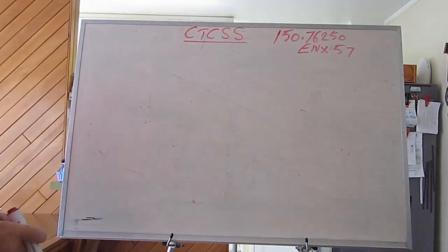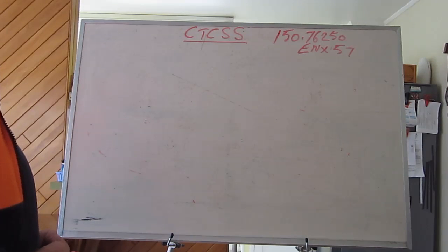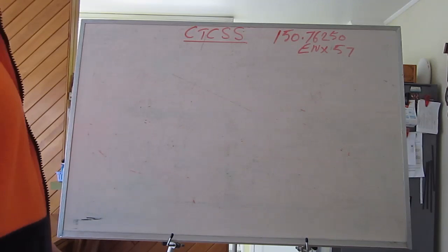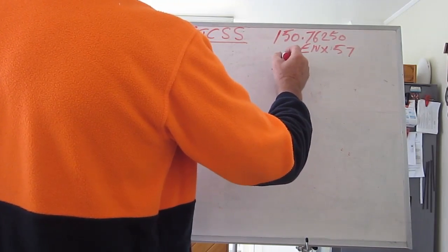and we actually have licenses given to multiple companies on this frequency. This example is quite a good one because it illustrates the kind of mess that you can get into with incorrectly programming CTCSS tones. I won't use company names.